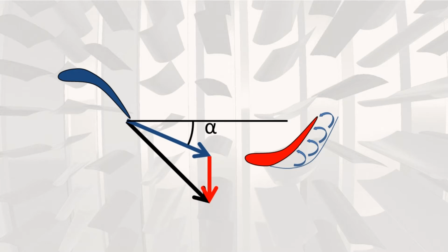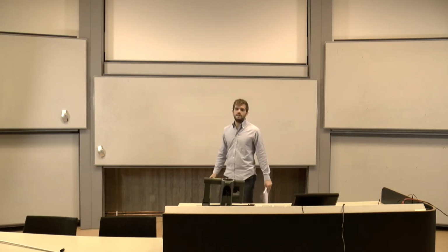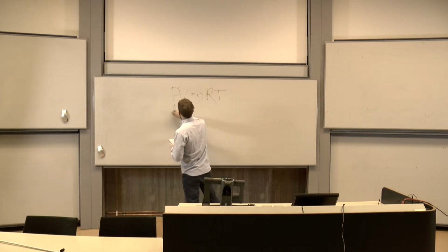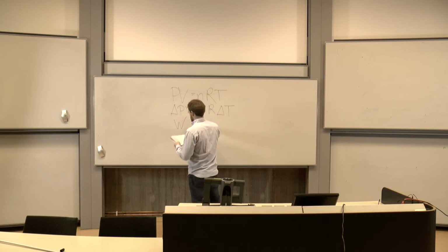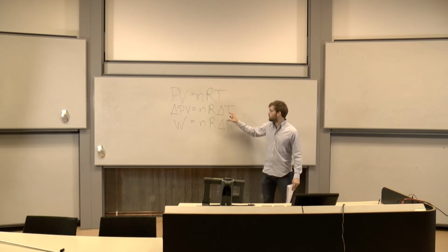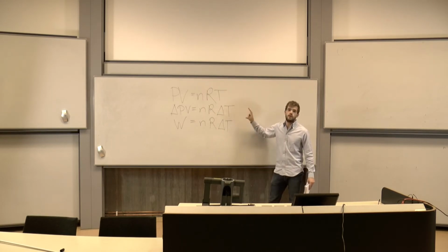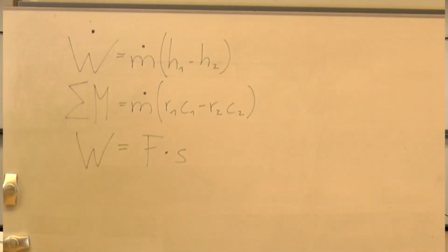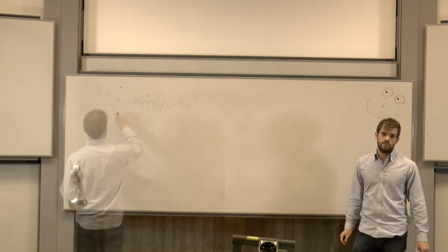In fact, let's take a look at how energy actually is extracted from the turbine. Using the ideal gas law, we can easily see where the work is coming from. The addition of fuel results in an increase of temperature and therefore allows for the extraction of energy. To show the connection to the blade design though, we need to derive some further equations, known as the Euler equations. We start with some fundamental equations.